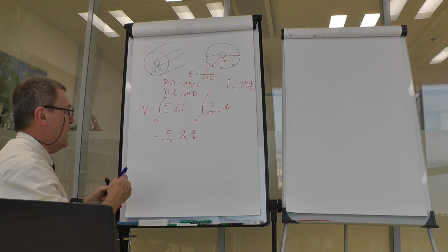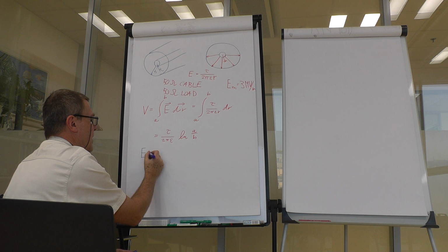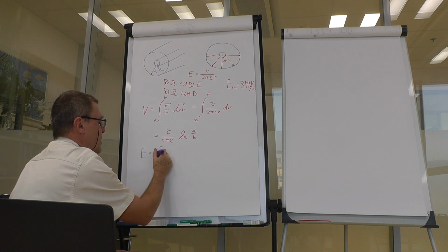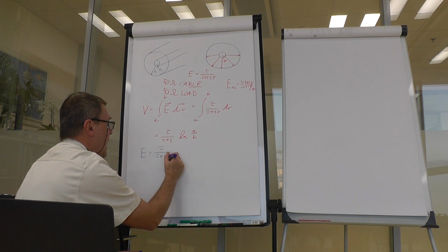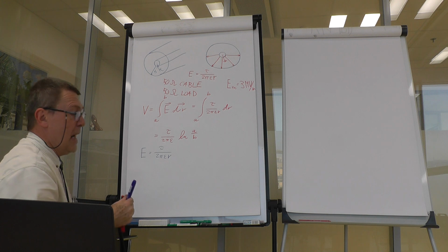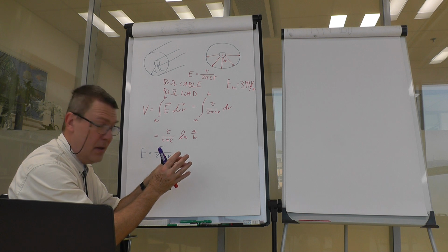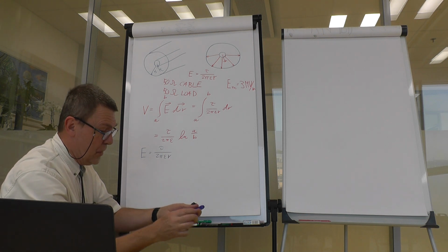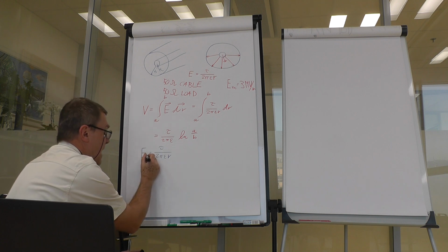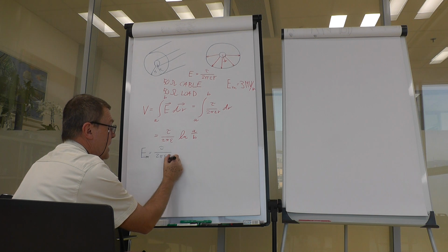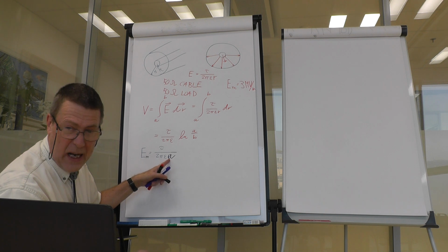And as we know that the electric field strength again is given by this charge density, that unknown one, over 2 pi epsilon r. And we know that the discharge first occurs at the surface of the inner conductor. We could put this equation a little bit more specific. So this is the maximum field strength, and it happens at the surface of the inner conductor. So we substitute A instead of r.